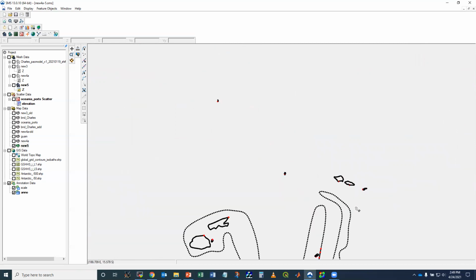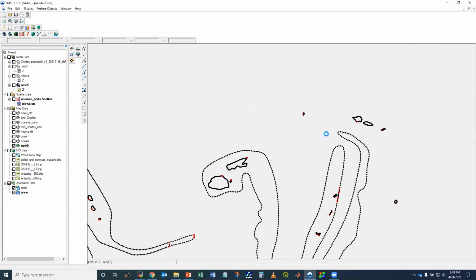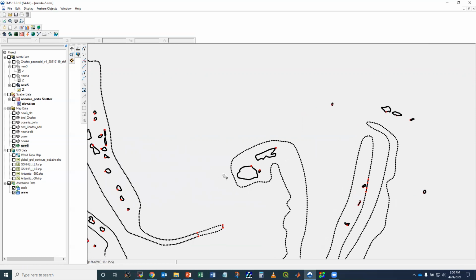Again, if the mesh resolution is not smooth enough and you have a problem, the model wouldn't blow up. You just see this kind of spurious process coming out very quickly, in a couple of days, no shorter, no longer than 7 days. So there's a problem, and you could fix the mesh locally.